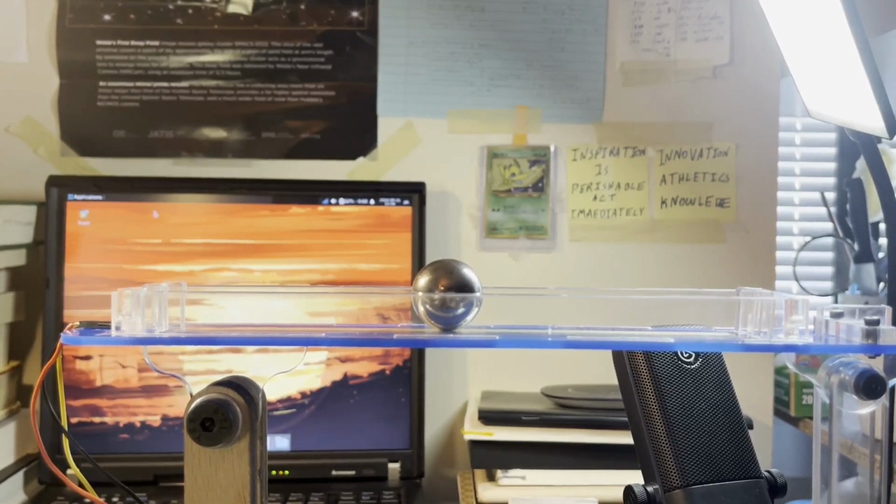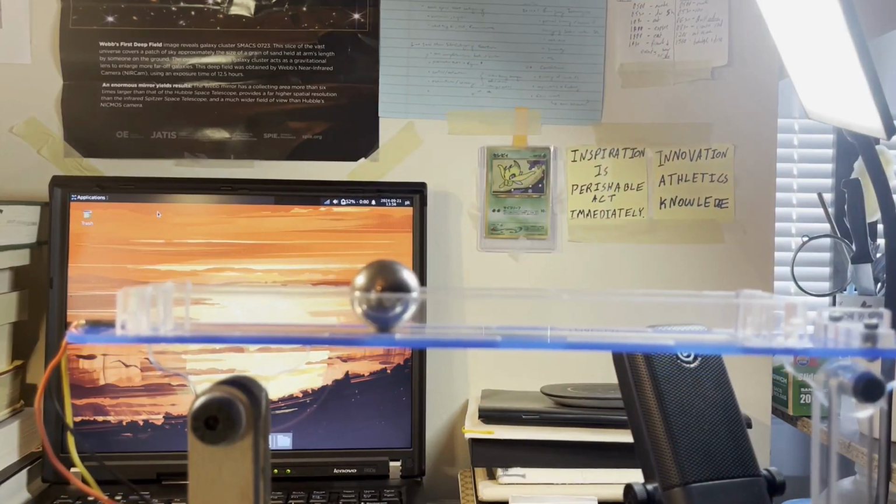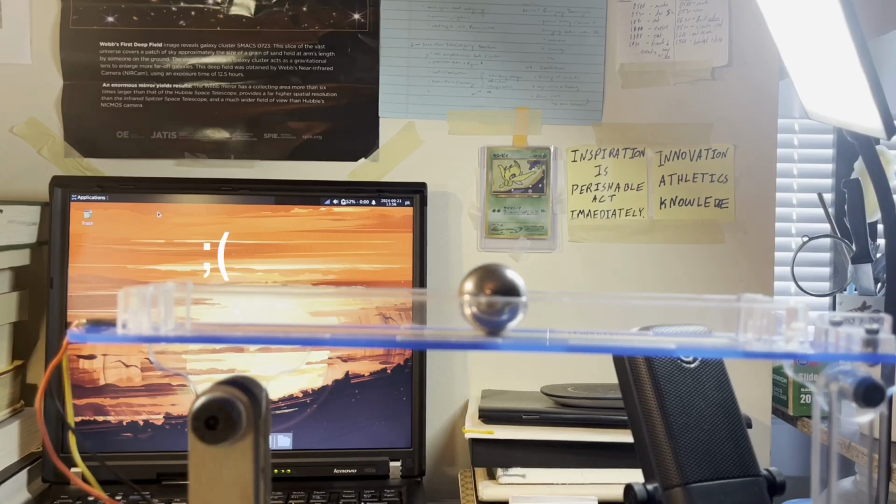Alright, to recap the tuning process, first tune Kp until your system is oscillating, then add Kd until your system reaches a steady state, and third, add Ki until your steady-state error is eliminated. Although the PID is old, it's used in practically every industry, so it's definitely worthwhile learning.